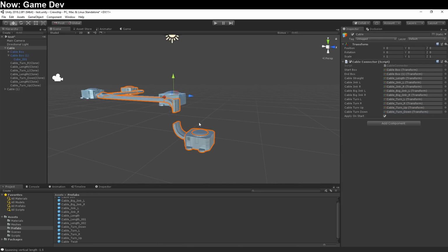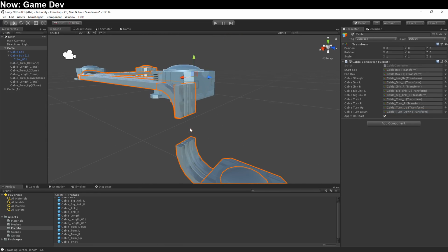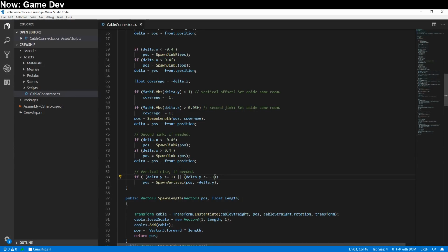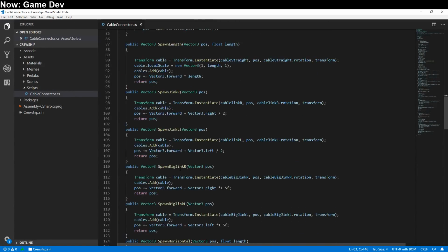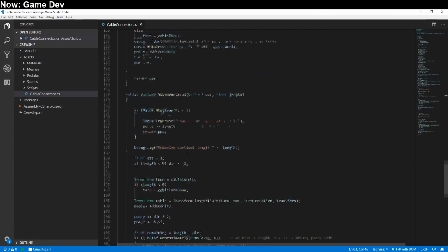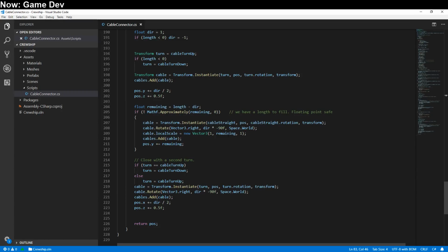There we go. So starting to get there, but this guy is rotated the wrong way. That's kind of odd. Is his scale inverted? Is that what's going on here? His scale's inverted. So when we do the scaling for these in both directions, we're going to want to do this as a mathf.abs.